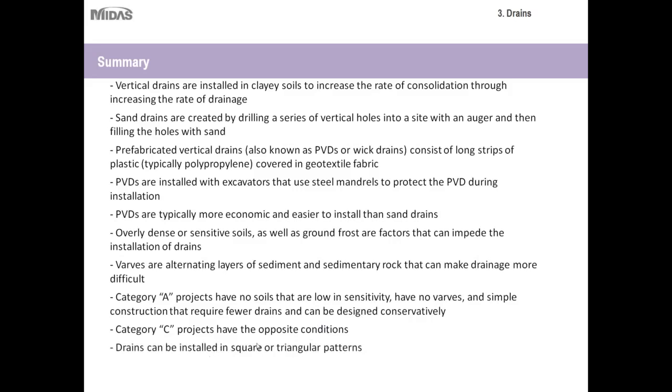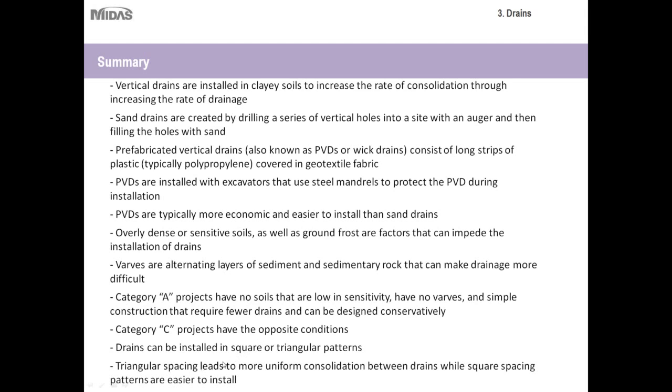Drains can be installed in square or triangular patterns. Triangular spacing leads to more uniform consolidation between drains, while square spacing patterns are easier to install. So once again, each one has its advantage.